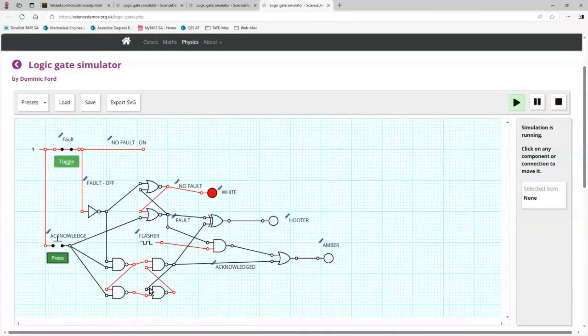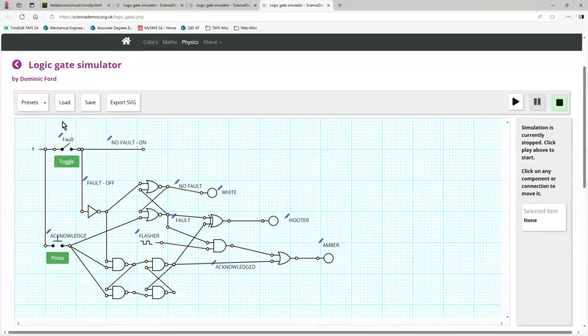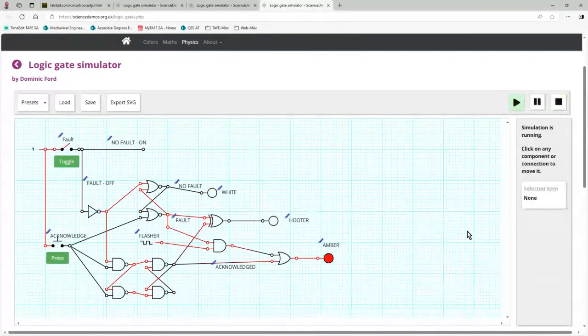So pretty much because of those manually built latches, there's unstable situations when you power everything on and you have to press at least acknowledge button to really reset it to normal. So I'll do it again. I'll stop the whole circuit. I'll start it. We've got unstable situation. I'll press acknowledge. And now we've got a stable situation. Now I'll reset this, acknowledge again, goes back to white.